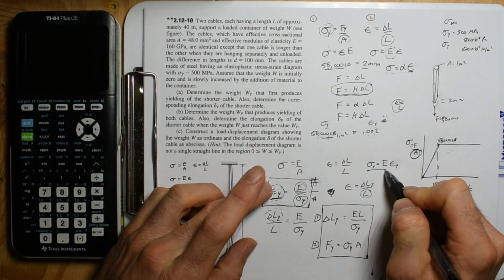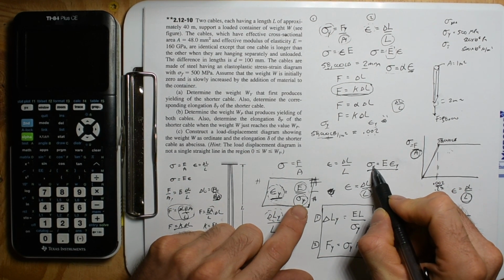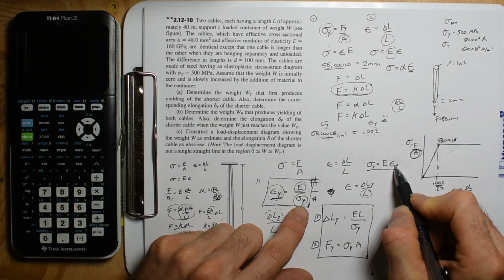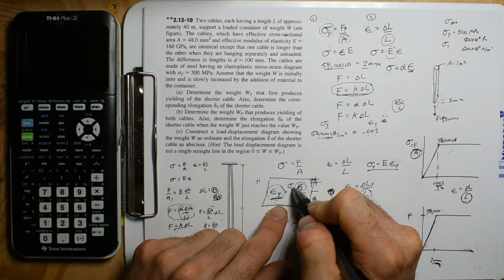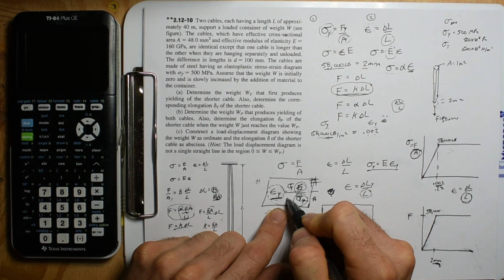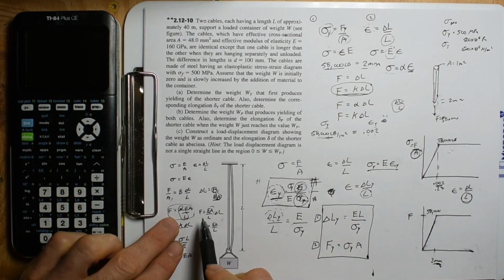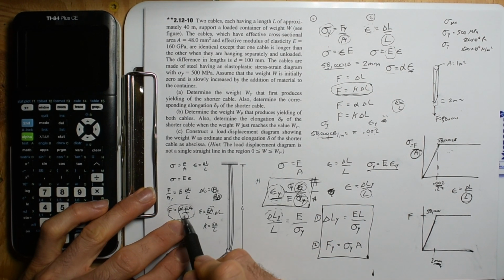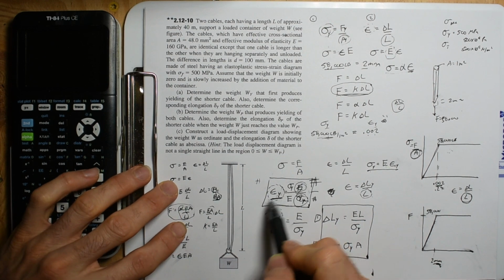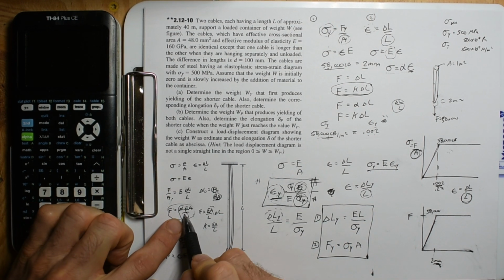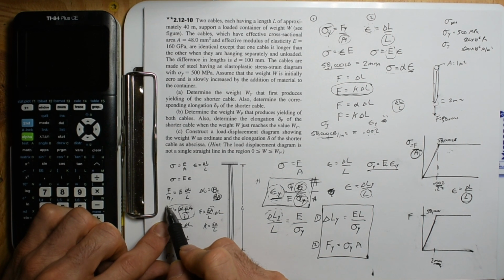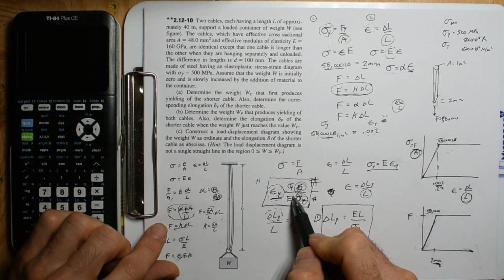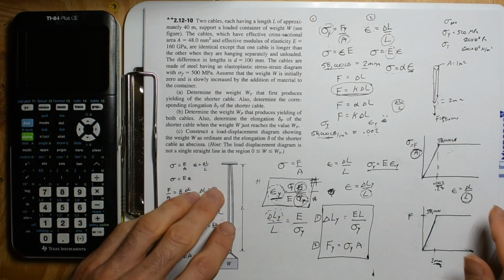I said, let's see if this is true. Yep, this is true, and we were trying to solve for this, so I had to bring the E downstairs. Yeah, so that was a good catch. So we have yield strength upstairs, E downstairs. Cool. And now I can see that if I want to get this, I'm going to have change in length over length. That's going to be my strain. I have to get E downstairs over there, and then A downstairs over there. And I'll have F over A, so I'm going to have strength divided by E. So all these combinations you can get.